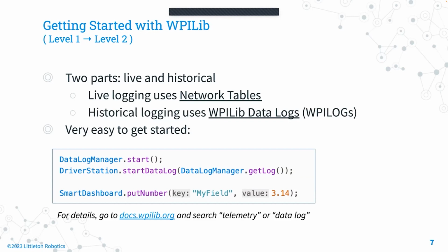WPILib's recommended approach is that you log all of the fields you care about directly to NetworkTables, which will then be captured and saved automatically to the WPILog. So it's really convenient, and I have a few lines here that demonstrate very simple usage. In the first line, we start a data log session, which will begin capturing NetworkTables data.